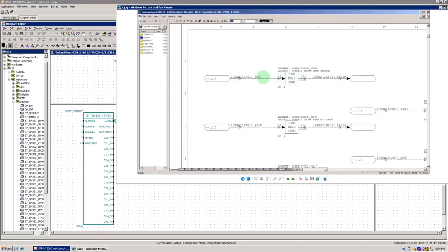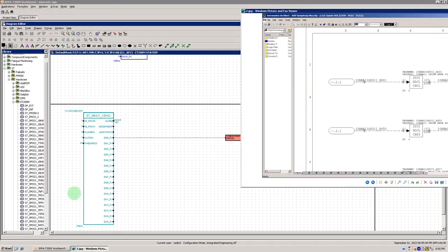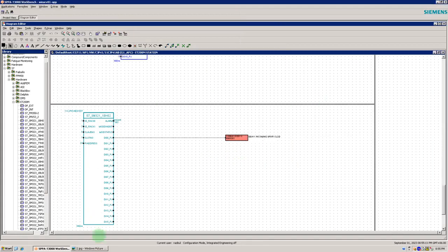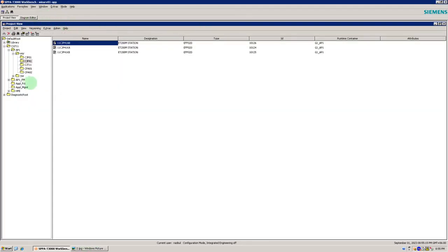Now the another configuration, what I need to do is to configure the alarming section here, right? So this is our software pages. That means that when the breaker is closed here, it will give me one alarm, and I can show that on my HMI page also. So to do that, I need to take one Boolean signal monitor, and before that I need to go to the software page.